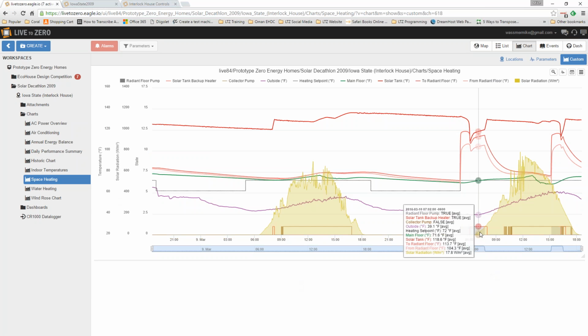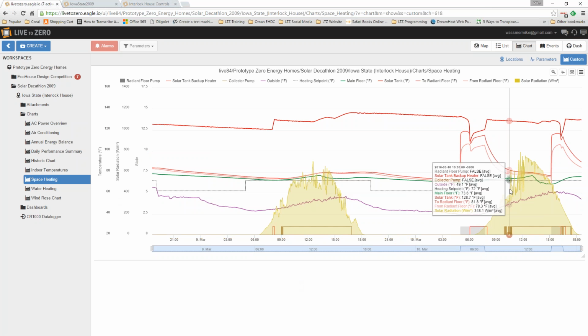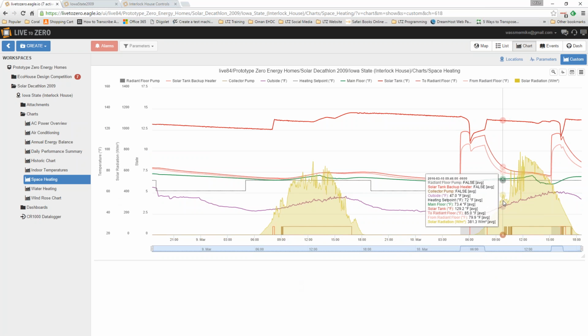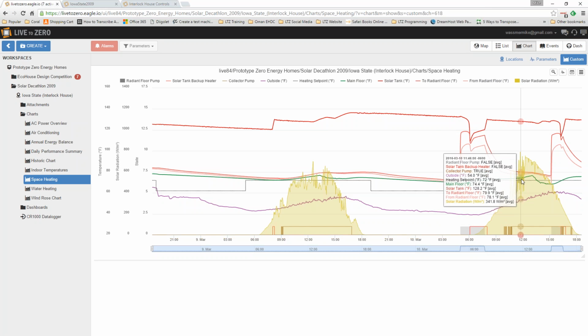So during the morning, what's happening is that because you use this heat for the backup heating element, the first chunk of the day, the first 2 or 3 hours or so of PV production, think of it as being spent on just recuperating what you just used for the heat. So we're not back at net zero until the middle of the day. Then everything we produce after that is contributing to an excess of power during the day.